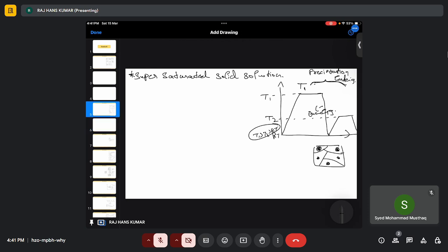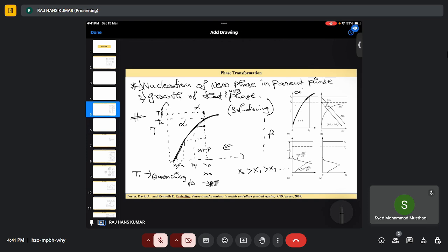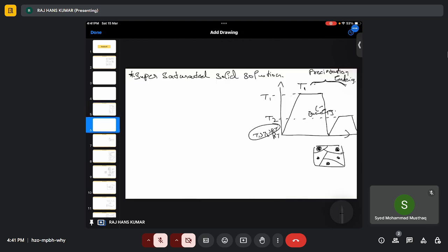Now, what are the different terms that it is going to depend on? Let's draw for homogeneous nucleation. So we know delta G total will be equal to minus the volume, let's say the volume of a sphere of radius r. So my volume will turn out to be 4/3 pi r cubed times delta GV, the change in free energy when alpha turns into beta.